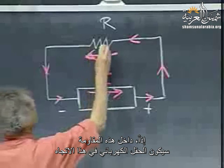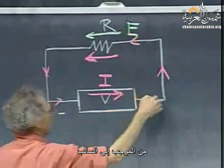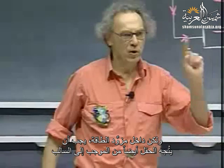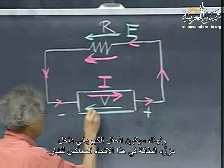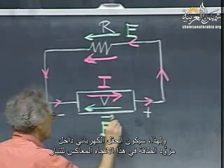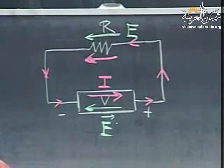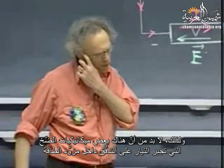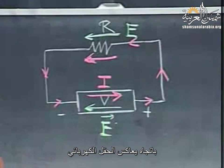So right here in this resistor, the electric field is in this direction, from plus to minus. But inside the supply, it must also go from plus to minus. And so inside the supply, the electric field is in the direction that opposes the current. So some kind of a pump mechanism must force the current to go inside the supply against the electric field.